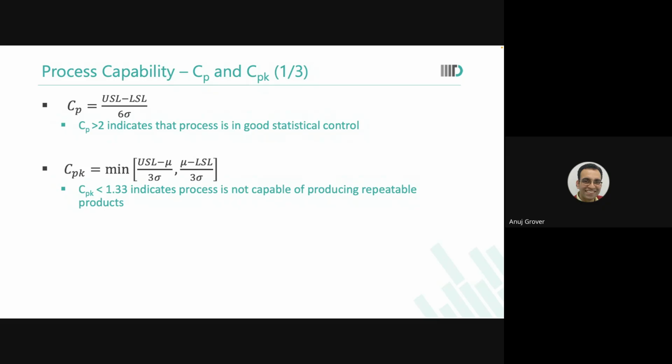Now reflect upon the initial exercise that we had done, where you made equations, and we said, okay, let VT be this, and now let us shift by plus minus 3 sigma, or plus minus 4.5 sigma. And you remember what happened to your SNM and write margins, the stability and writability? It completely went for a toss. Now, wherever your VT is, if this spread changes, again you are in a soup. So both these parameters jointly define process capability.